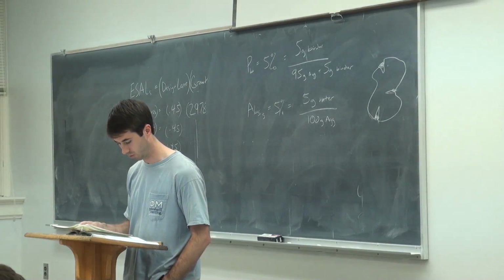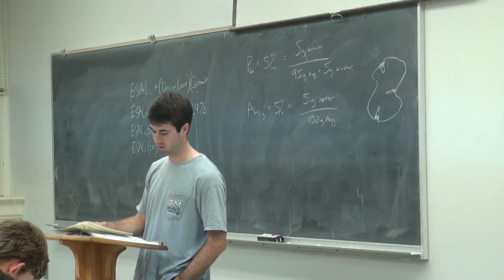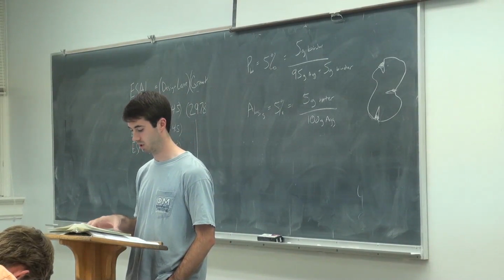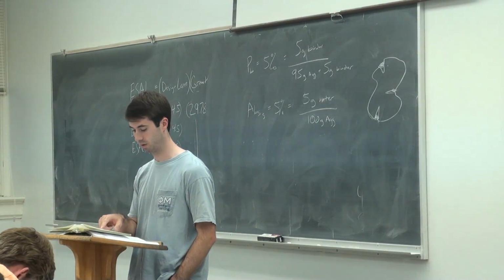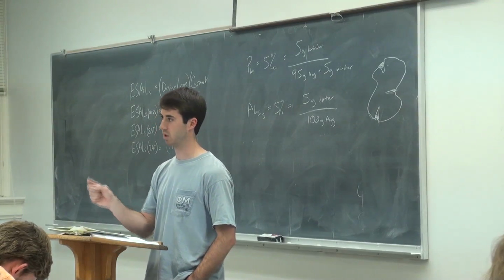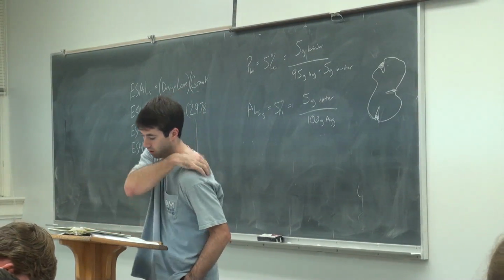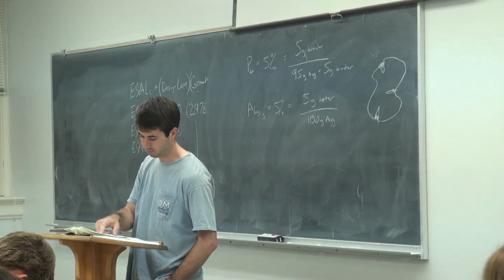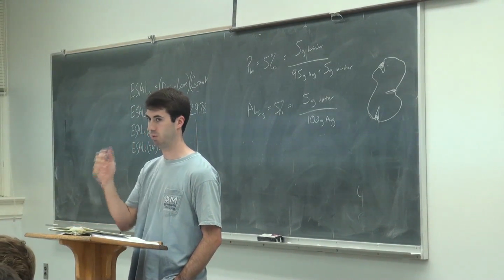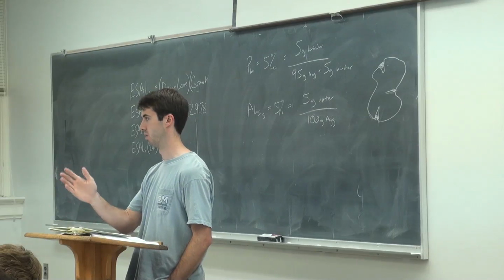This direct tension thing at the very bottom, they rarely run that, and I'd be surprised if they asked you about that. But if they did, it'd be the same system. If any one of these criteria fails, you have to go to the next temperature and see if it meets it at those, and if it does, you can claim it's that grade. So if you pass on the creep stiffness and m-value but fail on the direct tension, then you have to bump up the temperature grade, run it all again, and if it passes for all those there, then you're good.